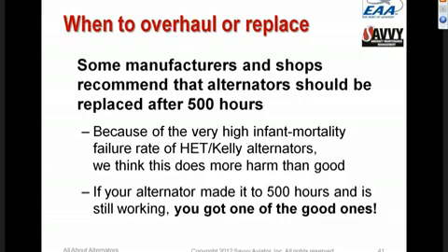And so if your alternator is working after 500 hours, you got one of the good ones, and we'd prefer you don't mess with it. We think that replacing alternators prophylactically after 500 hours is more likely to cause an infant mortality failure than it is to prevent an age-related failure.